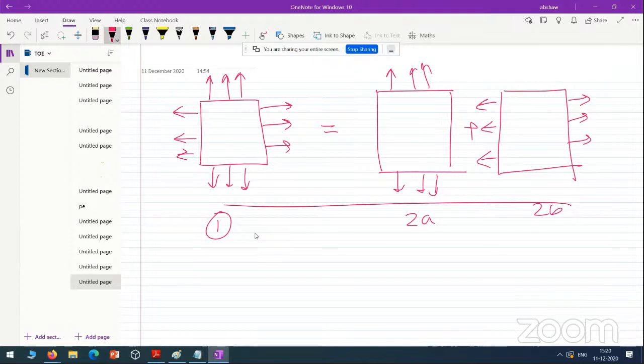Another thing: the bounds on elastic constants. If you recall, for an isotropic material we have two elastic constants, and in the class we discussed how, from a general anisotropic material, imposing several symmetries we finally arrived at the isotropic material. There are two elastic constants: Young's modulus and Poisson's ratio. Bounds on these elastic constants mean: what are their possible values?